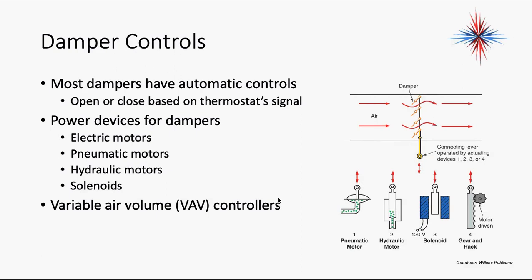In other words, we keep the temperature in the main ductwork standard, but we control the temperature in the room by changing the amount of air that's being allowed into the room. That's called VAV systems. You use them in heavy commercial, office, and big building environments, VAV. No thermostats around the spaces. We maintain the temperature by sensing the return air temperature from the building overall, and we allow different quantities of air to come into the space, and that's how we control the internal temperatures.